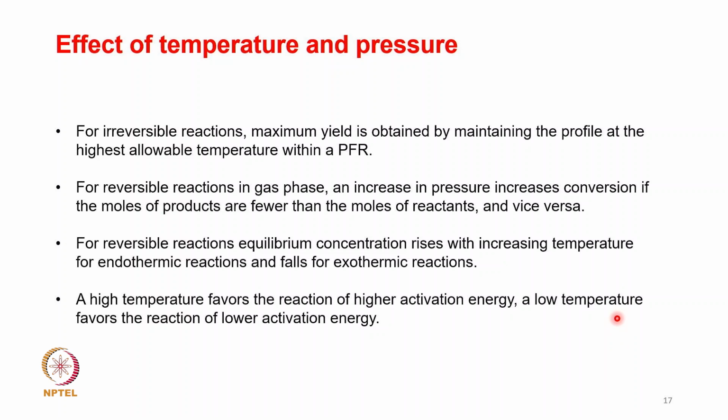And typically a high temperature favors the reaction of high activation energy, and low temperature favors the reaction of lower activation energy. So, in addition to whatever we have mentioned, which is of course just based on the geometry, the hidden factors which may play a role would be the effect of temperature and pressure. So, now let us look at another type of reactor which is known as a recycle reactor.